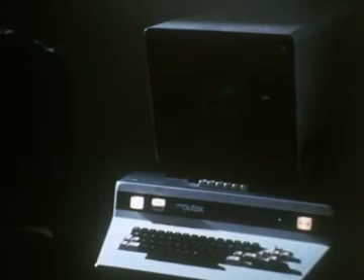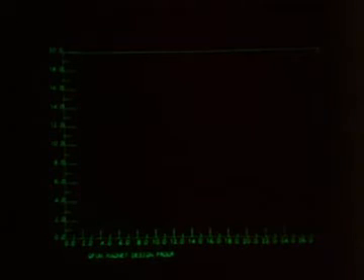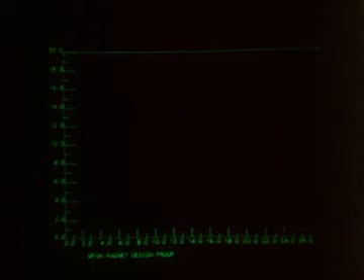The designer first of all sets up a graphical working space by typing in suitable coordinate limits for his problem. Next, the dimensions and the current density of the solenoid are typed in, and the program responds by displaying the cross-section. Because the coil has rotational symmetry about the lower axis, only half of the section is displayed.